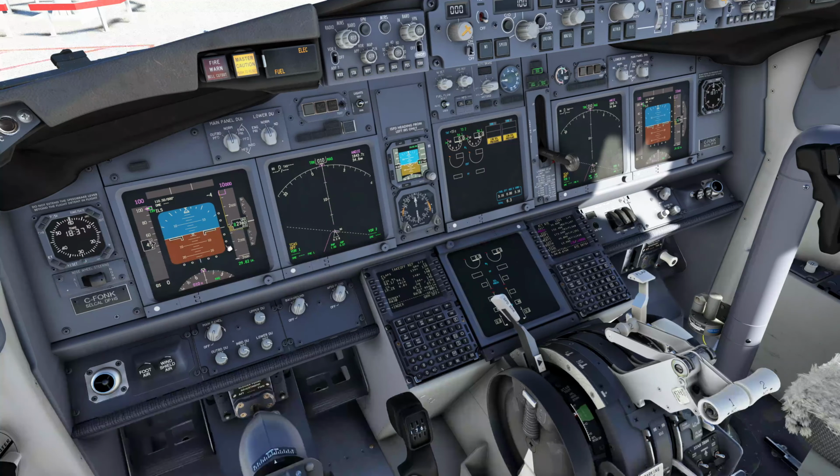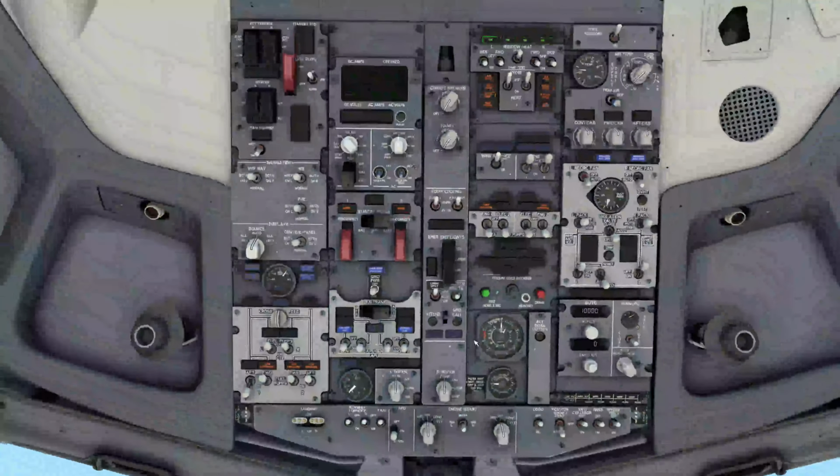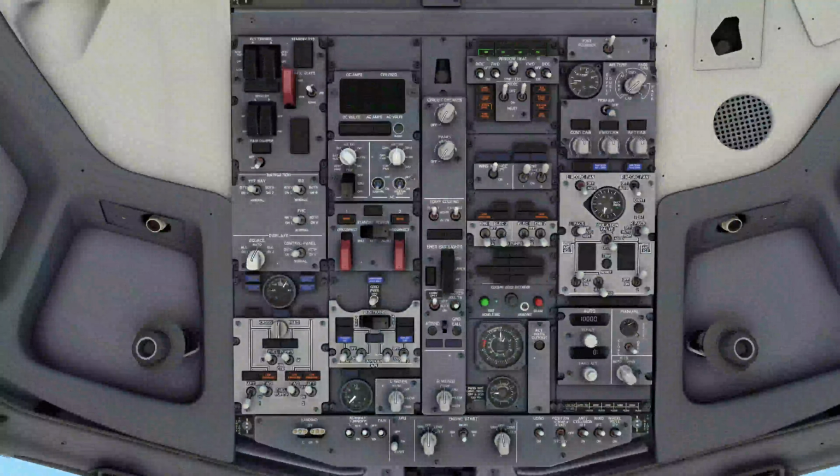Cruise altitude, pressurization panel and our landing panel. So as mentioned, we are going to 36,000 feet, so we're going to dial that in for the pressurization. Goes up by 500s. Now our landing elevation, we can set it later, but since we have the chart available, we'll look at it now. So the airport elevation in Vancouver is 13 feet, so we'll leave that at 0.